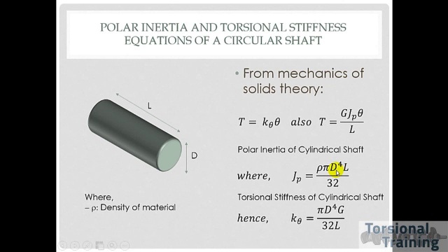If you increase the diameter of the shaft by 1 point, you're going to get, rather, to the power of 4 difference in the polar inertia. Similarly, with the torsional stiffness, if you actually increase the length of your shaft, then you're going to drop the torsional stiffness. But if you increase the diameter of the shaft, then you can significantly raise the torsional stiffness of the shaft. And I'll explain in some of the further modules why this is important. When we do some of the modeling and when you see some of the results, you'll understand why it'll be important to make some changes in your design phase, to accommodate certain torsional issues that can come up. So the best way that you can affect your torsional inertia or your torsional stiffness is by changing your diameter.